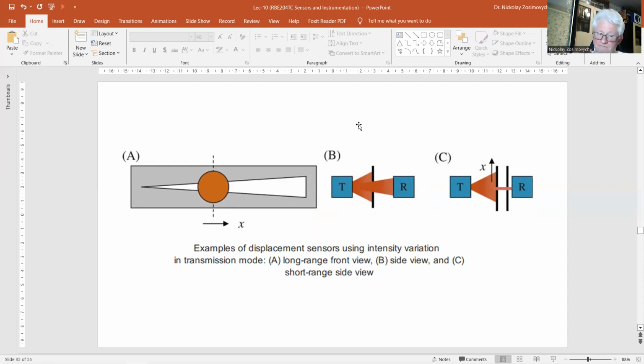And if we're using triangulation systems, they are less sensitive to the intensity of the reflected beam if properly interpreted. In the triangulation system shown in this figure, the PSD may be replaced by a diode array, which simplifies the interfaces, but the resolution is restricted to that of the array.